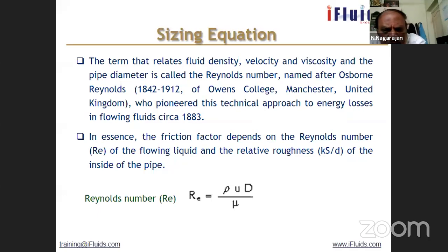So they approximately put, okay, consider 5 elbows, 2 T's, etc. When there is a branching in the pipe, they consider T's. So it's a little tricky subject, and it needs some experience, the estimation of the number of fittings.